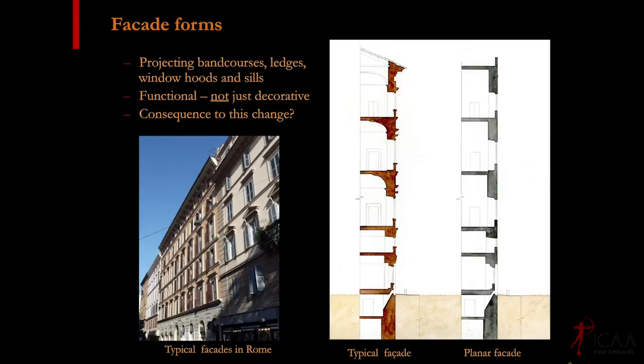Well, it is. The way these walls work, the technical term would be load-bearing mass masonry walls. So you have very thick load-bearing walls, which work structurally. A lot of these walls are 2 or 3 feet thick, solid masonry, and that works really well for carrying all the gravity loads of the floors down to the ground.